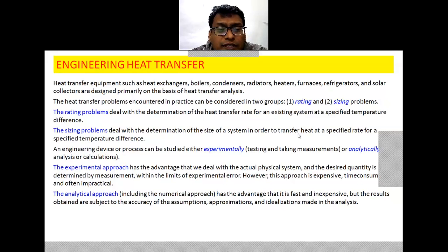So these are the two approaches, experimental approach and analytical approach. The designing is related to the rating problems and the sizing problems. In case of the sizing problem, log mean temperature difference has to be taken into account. However, in rating problem, you take the number of transfer units, that is NTU, as the basis for calculation.